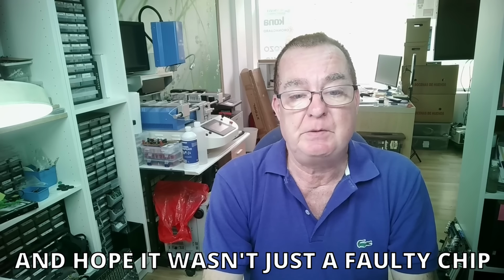If your graphics card basically showed there was a fault when we were testing the PCIe lanes, and especially the PCIe clock, then you almost certainly have a graphics card that is not repairable. And that's because the PCIe lanes and the clock go directly into the GPU. There's nothing in between really to go wrong. Yeah, look for a broken track, maybe if you really have the equipment, take the GPU off, reball it, put it back on, but that's not the sort of repair most people can do. So I think it's fair to say that if it has failed at this point, it's not something you're going to fix. You may be lucky. The other thing, you may have found some broken capacitors.